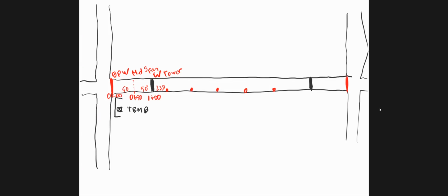All subsequent lights, the lab manual says 49.9. In real life, nobody would design lights 49.9 feet apart. They'd be 50 feet. All right. Somebody wanted to make more math for you, but all the distances and stations are given to you. Those aren't going to change. Okay. So then you'd have station 1 plus 23.9 right here.